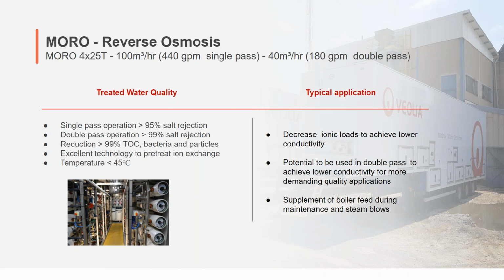If DI polishing or deionization polishing is still necessary, RO pretreatment to a DI will dramatically increase the demin capacity and run length, which translates into tremendous savings in regenerating or mobilizing mobile DI trailers.